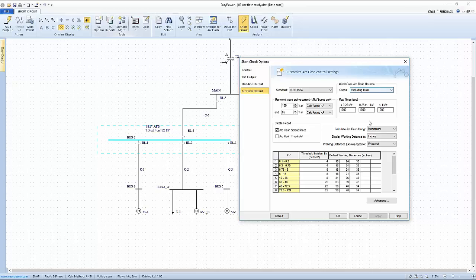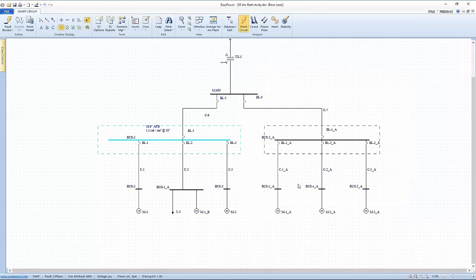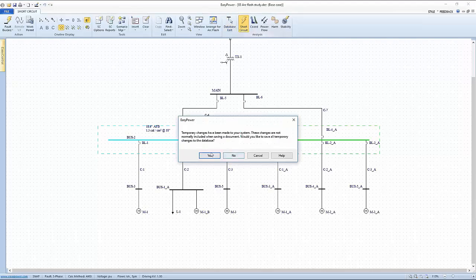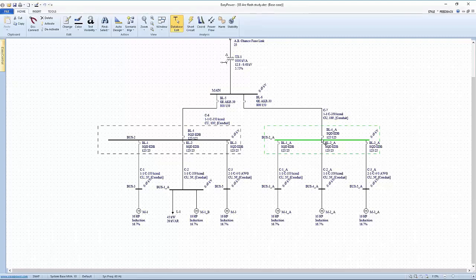So again, the recommendation is to set this global at what the average is, or most of the breakers in the panel are at, and then on an individual bus where, let's say for instance here, the main breaker does have a flash barrier, and we're not exposing workers to undue hazards, so this breaker will actually be included.